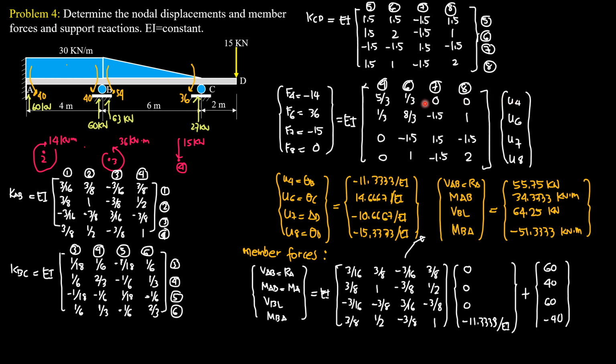And this is the value of the cells. For 4, 4, we have 1 here plus 2/3, so 1 plus 2/3 equals 5/3. 4, 6, we have 1/3 here. 4, 7, there's no 4, 7, so 0. 4, 8, there's no 4, 8, so 0. Then copy 1/3, 0, 0 because of symmetry of the system structural matrix.